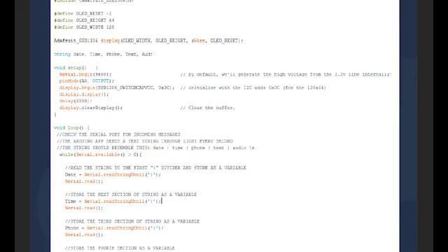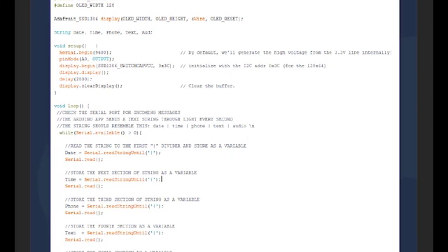We set the A0 pin as an output pin. We begin the OLED screen at address 0x3C. We display the Adafruit logo. We make it stay for 2 seconds and we clear it. And then we check the serial buffer whether characters have been received or not. That is, whether the solar panel is receiving light inputs.